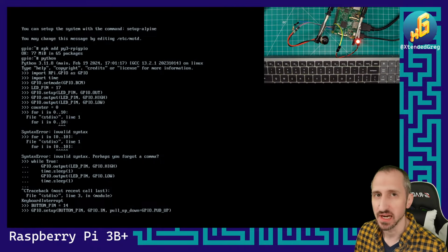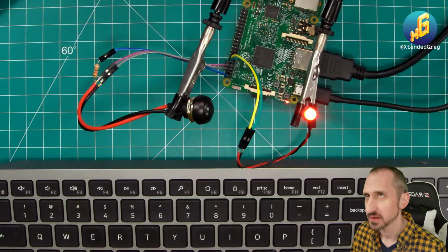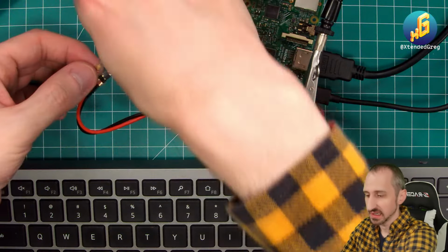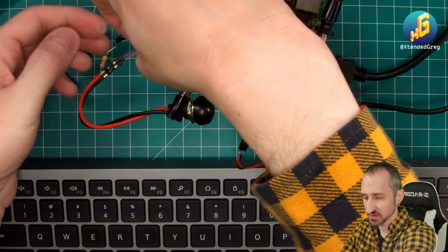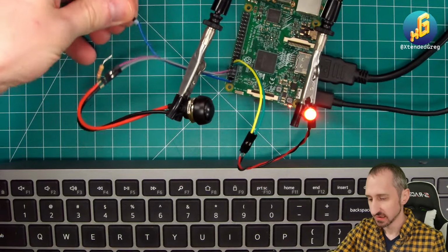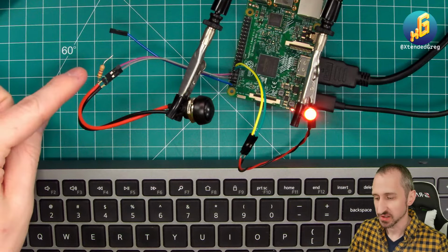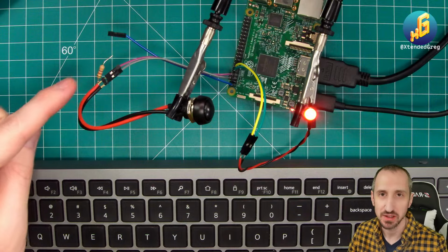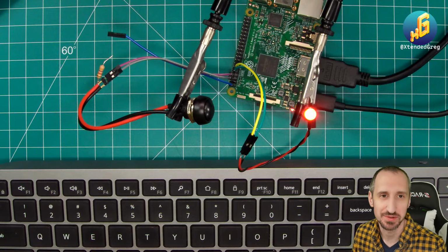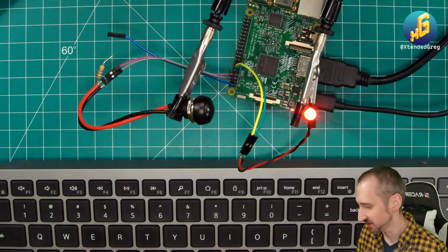All right, before I do that, let's go over to the overhead really quick. I need to disconnect this right here, okay? Because we don't want to add an external pull-up at the same time that we're giving it an internal pull-up. It could cause it to have problems. And actually, it could break your board. So be very cognizant of how you connect it.